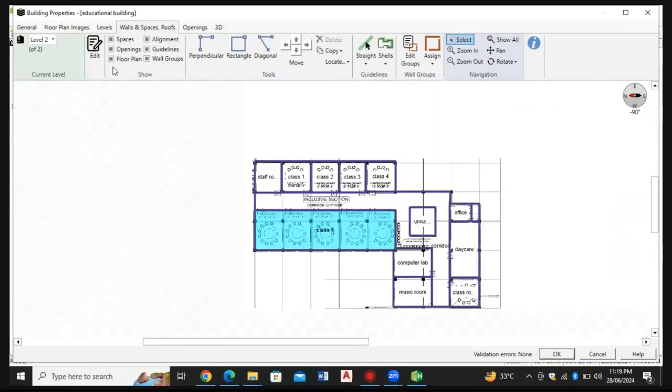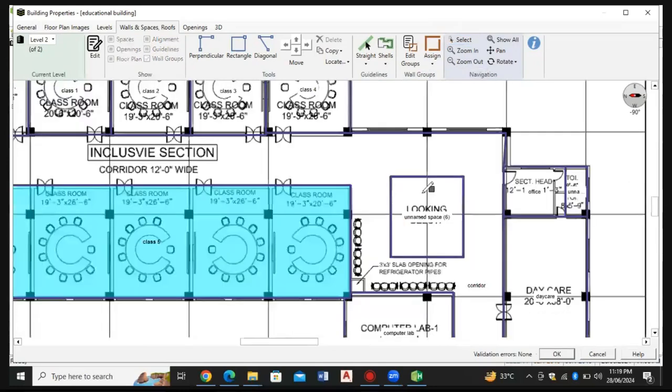Okay. What I have to do now is go towards openings. One more thing I have to tell here: HAP 6.2 has introduced air walls. It shows that you don't have any physical boundary, but there is a separation of air between two different thermostats.